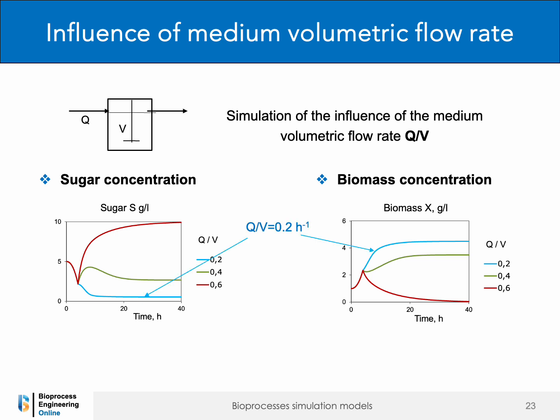According to the simulation findings, maximal conversion of sugar into bacterial biomass occurs at lower volumetric flow rates, indicative of an extended residence time of the medium within the stirred bioreactor. As the volumetric flow rate increases, there is a rise in steady-state residual sugar and a corresponding decrease in steady-state biomass concentration. Exceeding a certain threshold of volumetric flow rate results in a medium residence time that is too short for cell replication, leading to complete washout of cells from the fermenter. Therefore, continuous bacteria production can only be sustained at sufficiently low feeding flow rates.